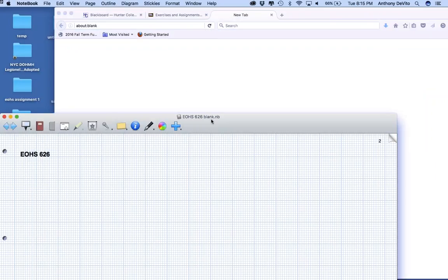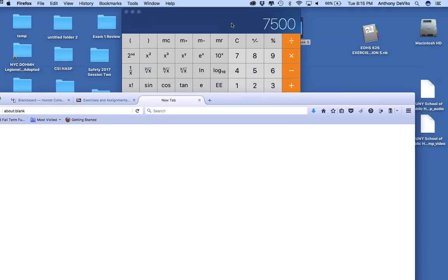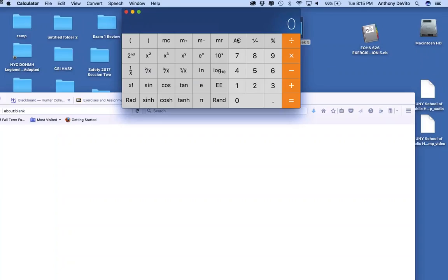How do we get 100,000? Okay, I'll back up. First we figured out what the area was. It was roughly 0.83 square feet, right? That's the slot. We said that air is moving through that slot at the rate of 2,000 feet per minute. So I multiplied that by 2,000 feet per minute, and this gives us the cubic feet of air per minute that we're moving.